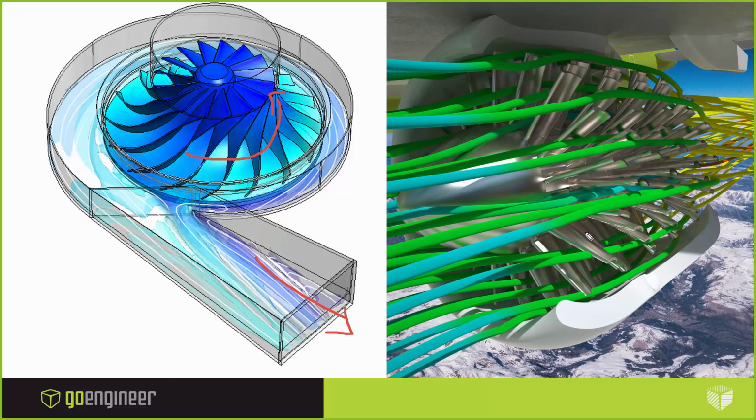And on the right here, we have a turbofan. Same thing, it's spinning at RPM, the other direction, and driving fluid, causing it to rotate. So what makes them similar is that they both rotate about a center line and drive fluid flow. This is the primary use case of rotating regions in flow simulation.